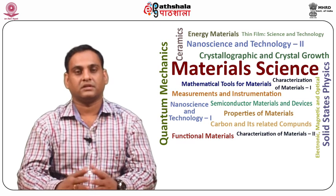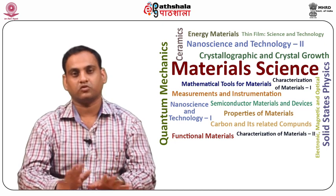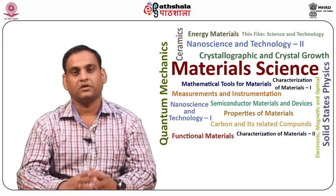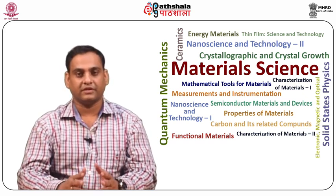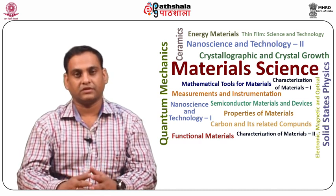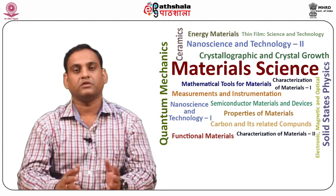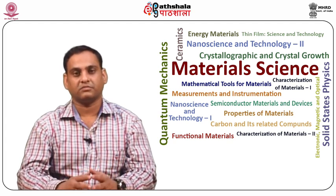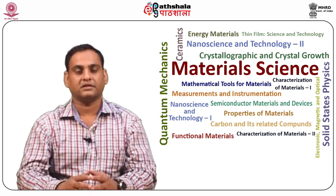Nickel-iron alloys. These alloys, known as permalloy, are extremely versatile and are used over a wide range of compositions, from 30 to 80 weight% of nickel. Over this composition range, the properties vary and the optimum composition must be selected for a particular application. The high nickel content alloys have high permeability. Alloys around 50 weight% nickel have high saturation magnetization, and low nickel content alloys have a high electrical resistance.